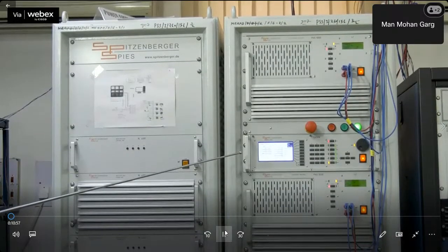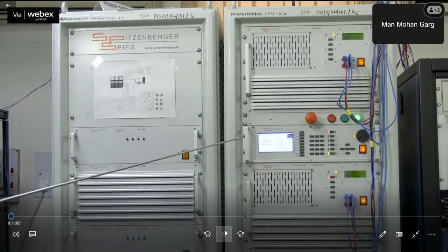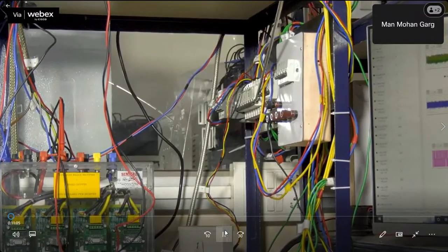While the stator of the slip ring induction motor is connected to the power amplifier via a switch, the switch is initially open and is further closed when the stator voltage and phase angle is synchronized with the voltage and phase of the grid using the rotor side converter. After synchronization, RSC regulates DFIG to operate in the speed power control mode.